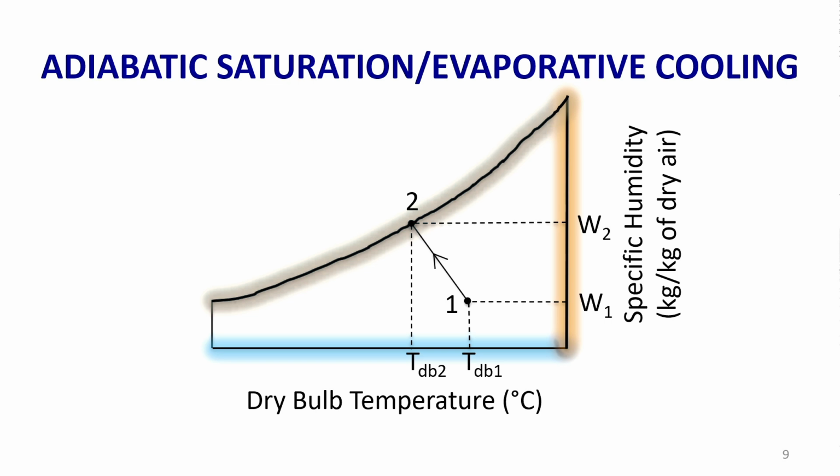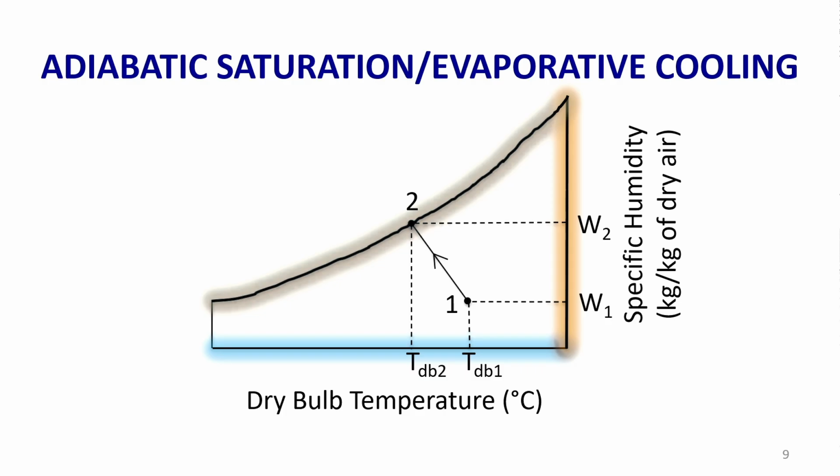Evaporative cooling is used in cooling towers, where normally what happens is that the water after cooling the condenser has a higher temperature, so it is sent back to the cooling tower, where it is cooled by the air. The air picks up the heat from the returning water from the condenser, and it cools the inlet water supplied to the condenser; again the water is circulated back. So, here during this process the enthalpy remains constant, which is entirely different from all the previous processes.